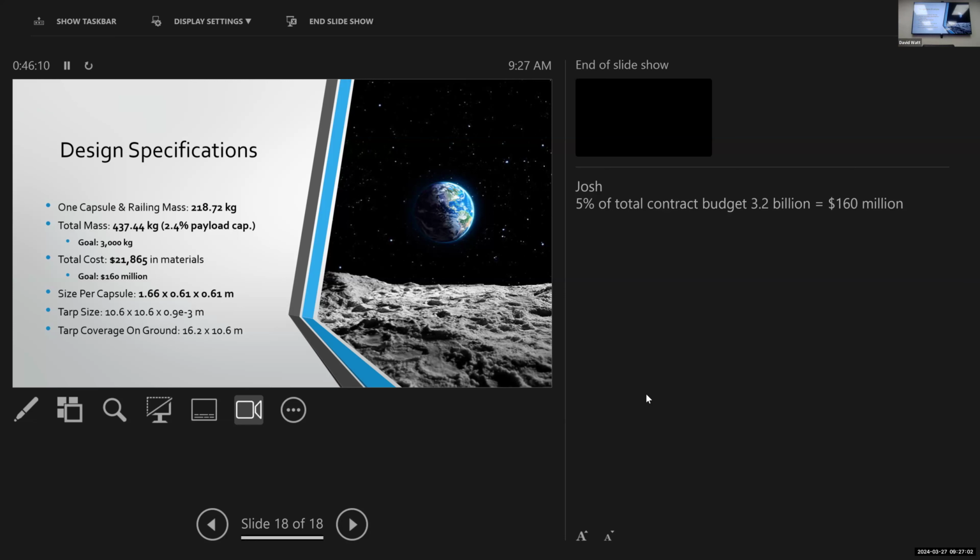Roger that. Just eyeballing it, getting scale and thicknesses of everything is difficult from a presentation like this. But if you're deploying a 9 kilogram tarp, or two 9 kilogram tarps, that just seems like a lot of additional structure to support that. I think I got you. Roger that. Yep, I think that should be lower. Not that you didn't measure the mass of what you got correctly, but you'd probably design something lighter to effectively deploy it.